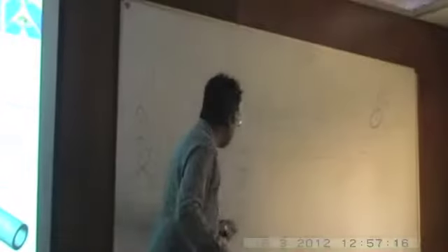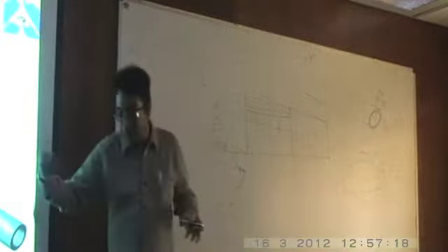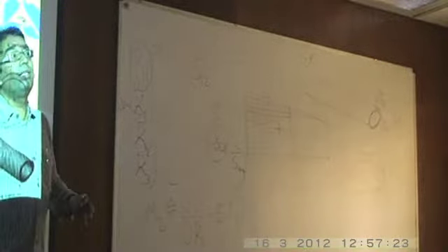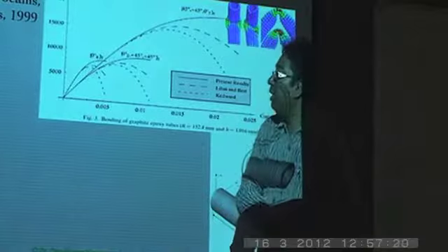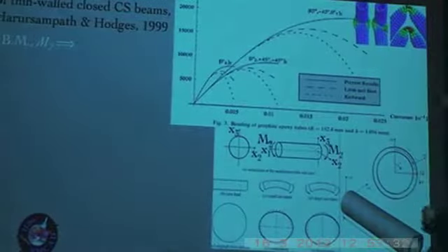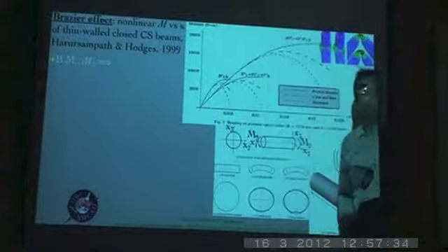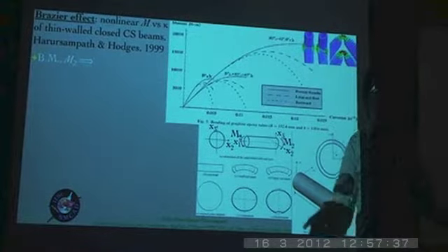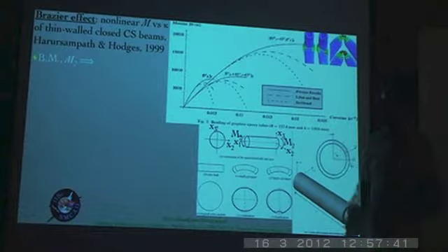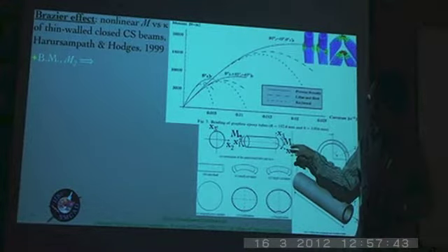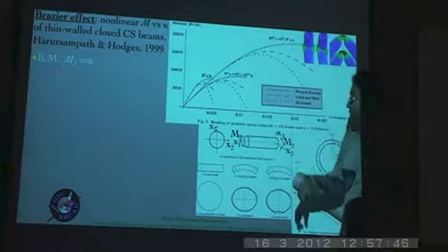In an isotropic beam it is EI2, but it's more complex than this, not overly complex, in the case of a composite tube. Again, depending upon the layup and the material properties, that can change. So the whole idea is this: you apply a particular bending load that causes a bending moment, which is a stress resultant in the sense of the beam. Then you have that bending moment M2, which is about the X2 direction.